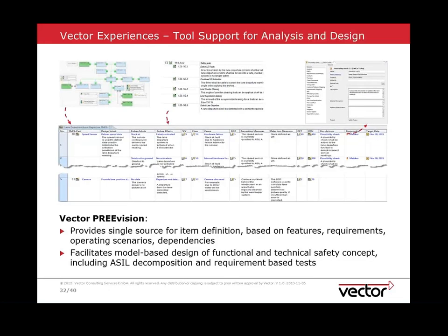Or if we go a little bit more into the design, the support for analysis and design could, for instance, mean that dependencies would be adequately managed, and that the functional and technical safety concept, including the ASIL decomposition and the necessary test cases, are all lined up. Therefore it's a good instrument, and also to see how in the life cycle the different safety requirements are addressed.